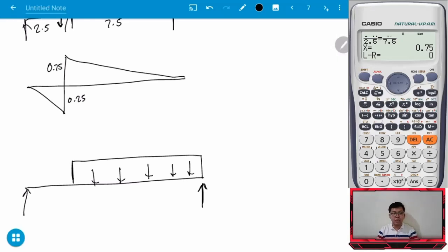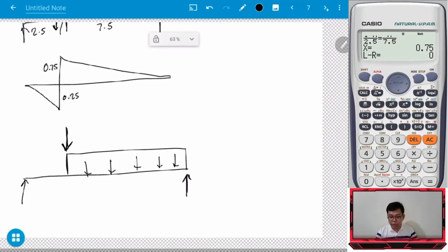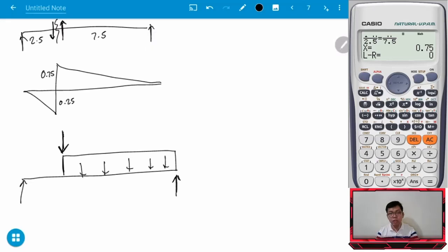Now, ang tanong, asan ko ilalagay yung concentrated load ko? Now, sabi kanina, the value daw of the function is equal to the concentrated load multiplied by the ordinate. So, to get a maximum value, try to put the concentrated load sa maximum ordinate din. From our figure, saan dyan ang maximum positive ordinate? Obviously, nandito. So, ilalagay ko yung load ko dyan. Therefore, ito yung mukha ng beam mo, ito yung mukha ng loading mo, para makakuha ka ng maximum positive shear sa point C.